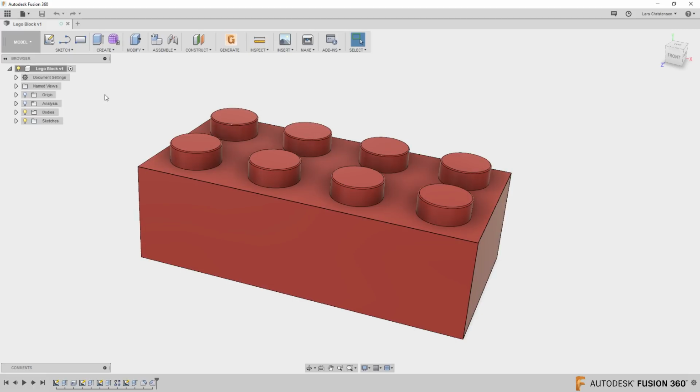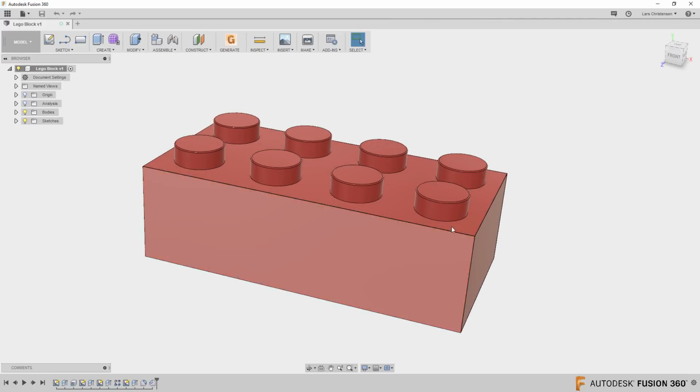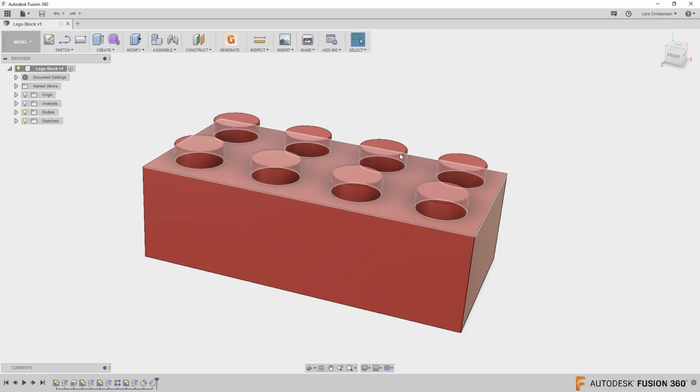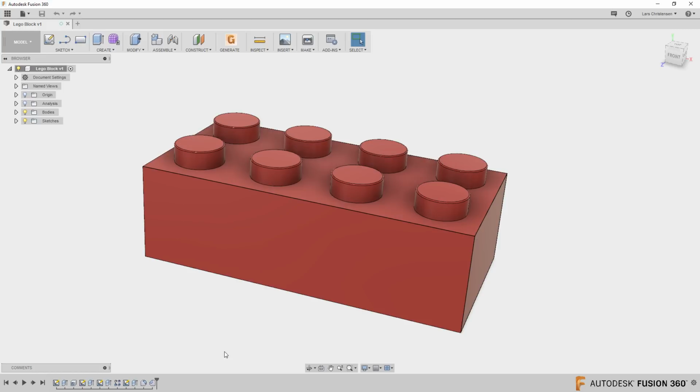You probably have more than a couple of options, but my preference is either I apply it to this model here, so let's picture that this is the customer who sent us this file, or I create my own copy of this one that I then mess with, if I don't want to mess with the customer's file. Because of course, if I start adding shrink factors and draft to this part, I'm messing around with the customer's model, though with a feature tree you could always roll back.